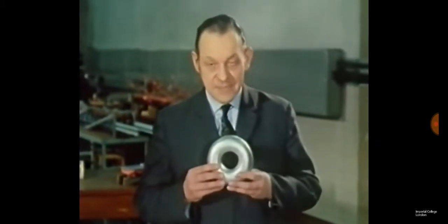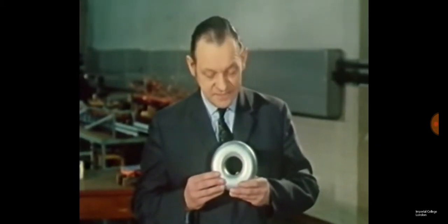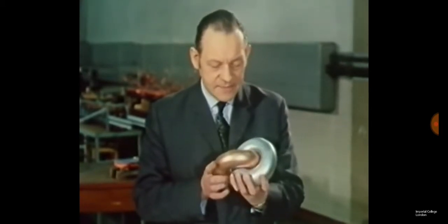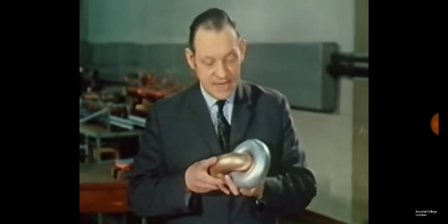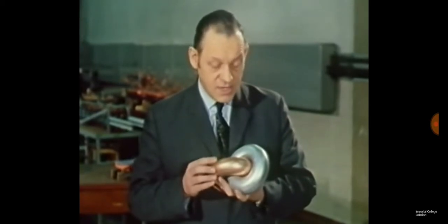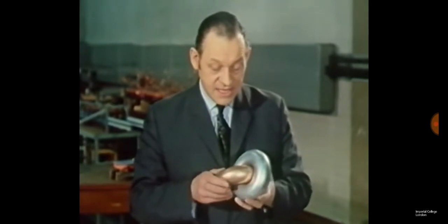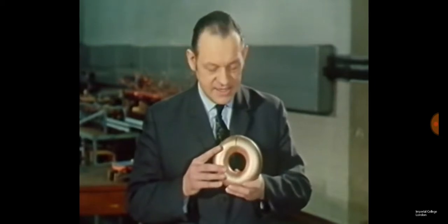Now, every machine has a magnetic circuit which I represent like this. The flux in that circuit is made to induce a current into an electric circuit which links it, like that. The force you can get from a machine is proportional only to the product of the flux in the magnetic circuit and the current in the electric circuit. So flux and current are the things you want lots of. The thing which stops you having as much as you'd like, of course, is the resistance in the case of the electric circuit and the magnetic resistance, or reluctance as we call it, in the magnetic circuit.